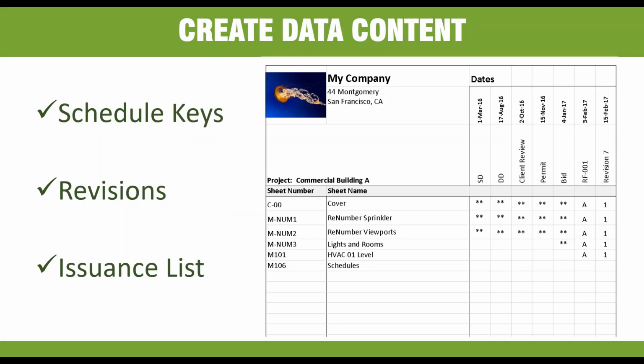In addition, if some of you are doing things like revision per sheet, where you actually have to get the revision data that's on each and every sheet, BIMLink can help you gather that data, and then we actually have made a macro template that can take that data and formulate it into a schedule in Excel, and then we can use Ideate Sticky to bring that information back in as a sticky, so you can stick that schedule on, let's say, your cover sheet.